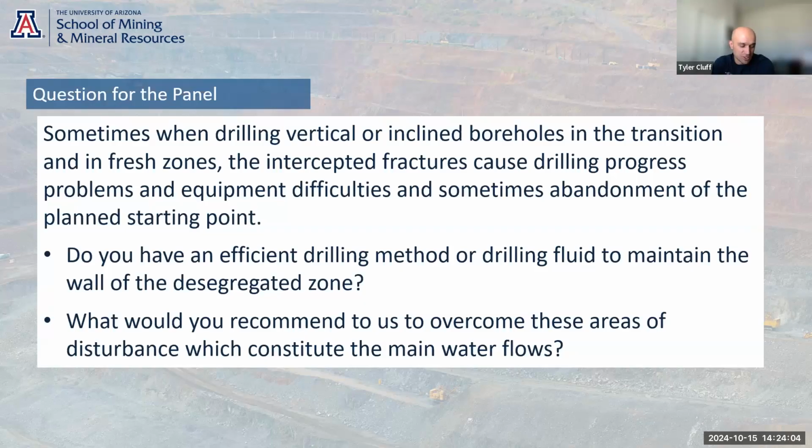Well, I was going to just chime in that in some cases we've had kind of good success with dual rotary, that method, and I've been surprised that the cost differential in some parts of the country is actually quite similar to RC drilling. And that again goes to supply and demand and the availability of the rigs. But if you are having that, that's something to think about and cost out with these advanced casing methods. In some places they're available and not that expensive.